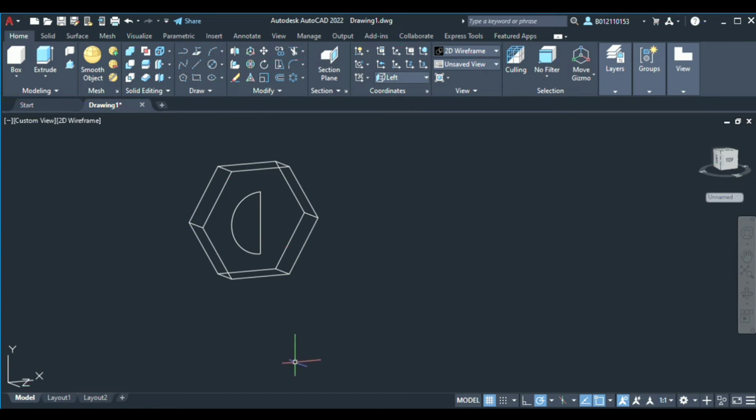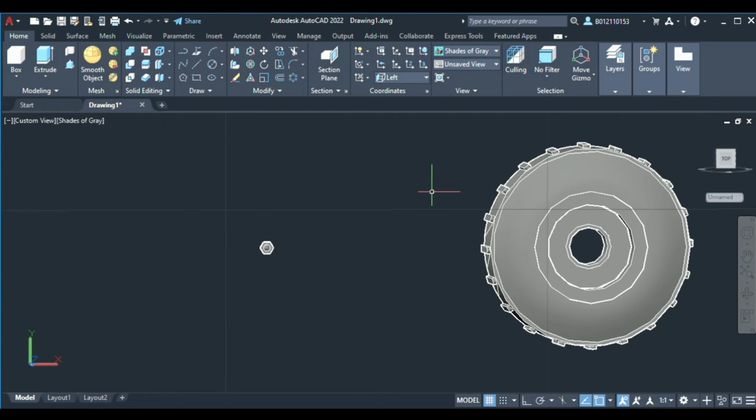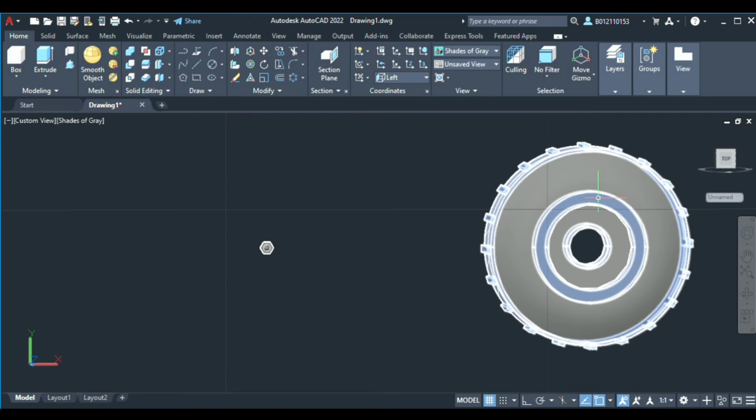Okay, and then again use the revolve command. Just type revolve and select this half circle here, and then revolve from here until here, and then it will be around there, and then you get this circle. Okay, so now we need to make this thing here. We need to move it, but first we need to make a part for this, which will be filleting this circle. Yeah, I'll show you how to do it.